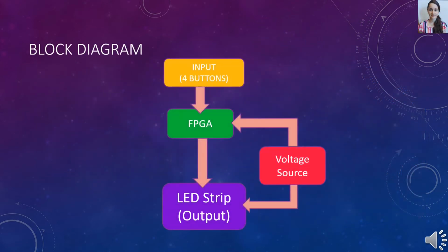In this block diagram, the basic outline followed for the assembly of the prototype is shown. As seen in the yellow block, the user will have 4 options to choose from, which will assign and feed parameters to the FPGA to calculate the corresponding wavelength shift with the object viewed moving towards or away from the viewer. Once this calculation is done, the appropriate delays of RGB values are fed to the LEDs, where the visualization takes place. As for power requirements, a 5-volt source will be fed to both the FPGA and the LEDs.